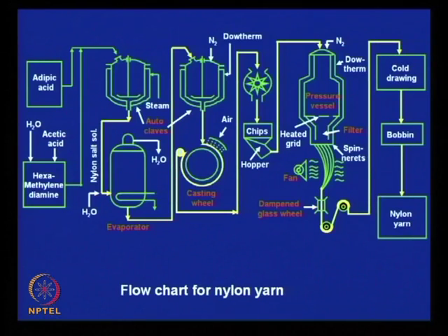You have seen, even if you go up to 99% conversion, you may not get high molecular weight polymer, provided you do not have this 1:1 or equimolar ratios of the reactants accurately taken. And again, that is a difficult task during weighing of the raw materials, say adipic acid and hexamethylene diamine. During weighing, some quantity of any of these two may be less or more other than equimolar